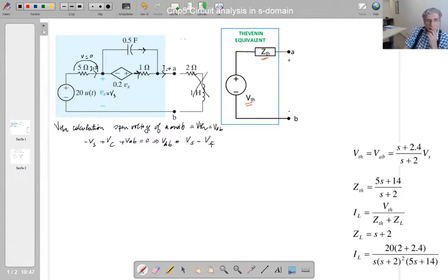So how am I going to calculate this capacitor voltage here? If you write Kirchhoff, there is no current here, no current here. So in this loop there is no current, but in this loop there is a current. How did that current come in? Since Vx is equal to Vs, this dependent voltage source voltage is equal to 0.2 Vx. That means 0.2 Vs, isn't it? So this becomes a source. This source delivers a current to that loop, isn't it?